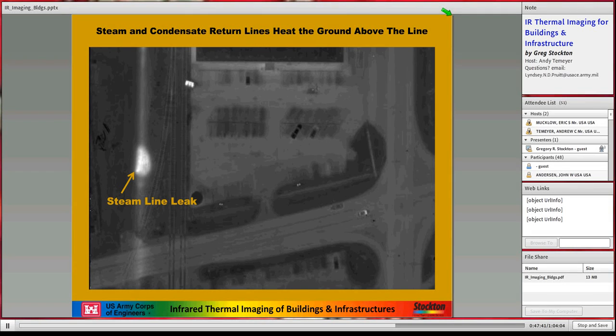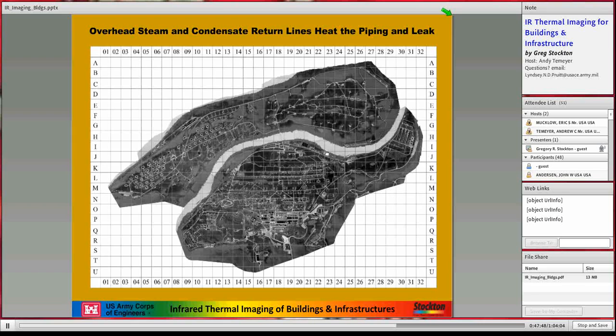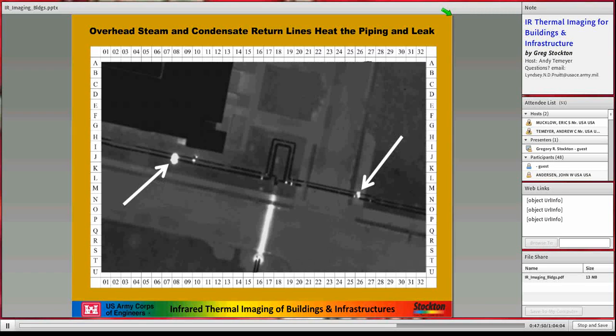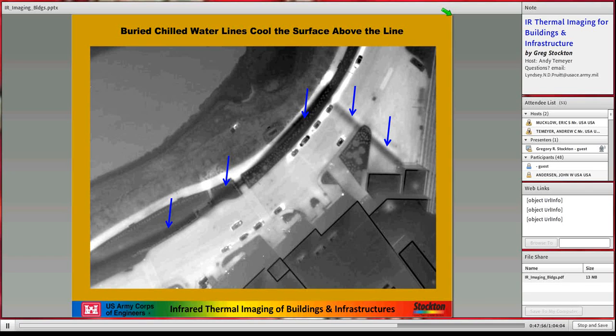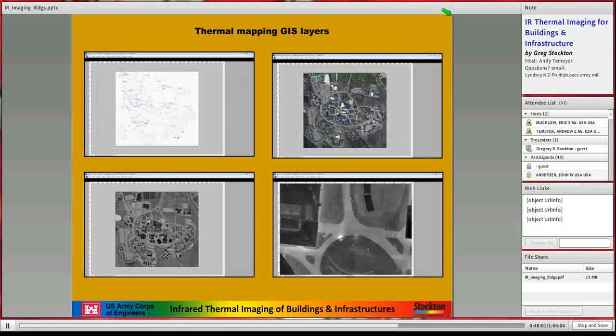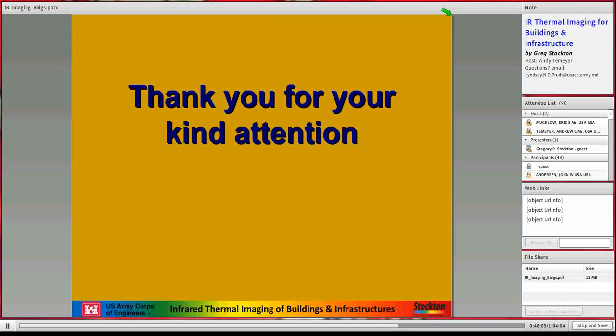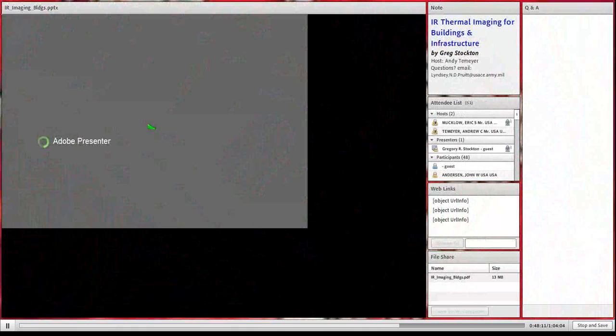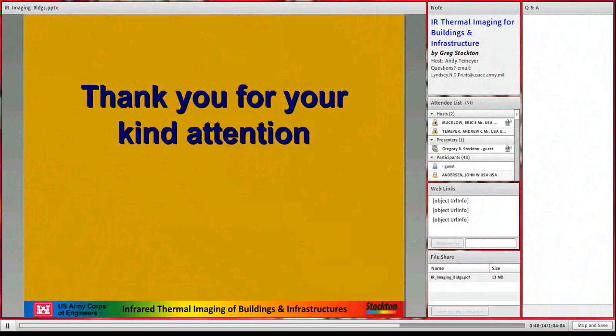Now, this is what a steam leak looks like. This leak is $30,000 a year, and it's the size of a pencil lead. This is really tremendous savings from finding the leaks. When it comes to finding areas that have less insulation or deteriorated insulation on the steam line itself, there's a lot slower payback because you've got a bigger investment to fix it. But steam leaks are a no brainer. Find them and fix them.